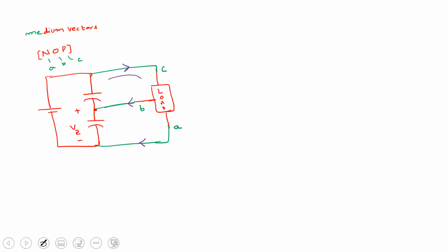No, sir. If this is the incoming current, we cannot confidently say which way the current is flowing out. Because two phases are there, A and B, depending on their instantaneous values, it can be determined in which phase the current is exactly coming out. So we cannot say that this current is flowing in this direction or in that direction, but definitely there is a flow of current. The C phase current is split into the A phase current and the B phase current. But their instantaneous polarity all depends on their instantaneous voltages. Therefore, we cannot confidently say the current direction.